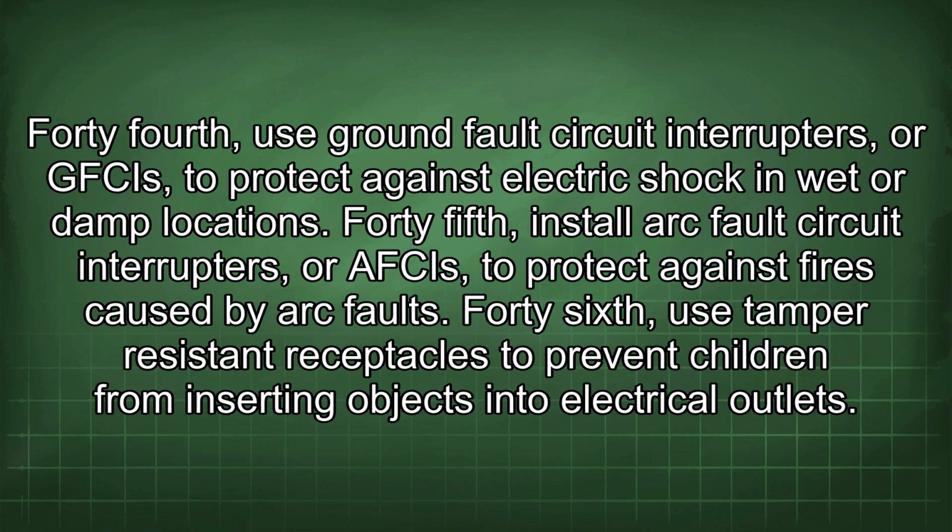44th, use ground fault circuit interrupters, or GFCIs, to protect against electric shock in wet or damp locations. 45th, install arc fault circuit interrupters, AFCIs, to protect against fires caused by arc faults.